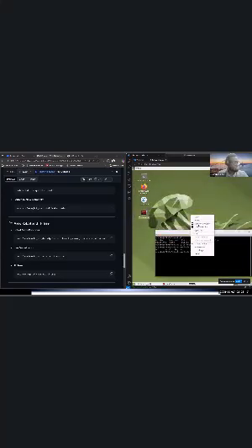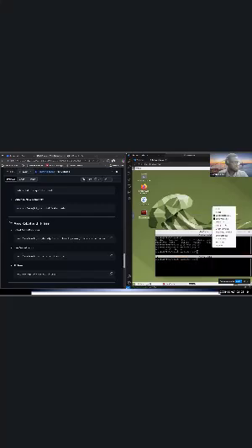We're going to split this terminal, let's say horizontally, then vertically as well, so that we can multitask, parallel programming. The first thing we're going to do, like I said, is it's very important to source your workspace. So if I do ls, src, I just need to do source install. I can close one terminal first, so that when I do a repetition, all the terminals are already sourced.